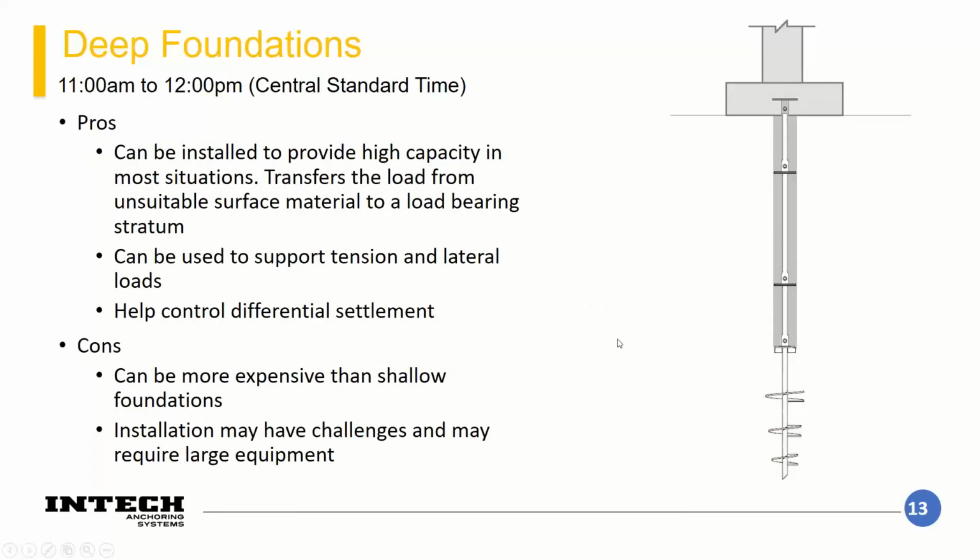So pros of deep foundations, they can be installed to provide high capacity in almost any situation. Eventually, you're going to run into some material that is either stronger soil or rock, and when you hit those materials, you'll eventually be able to get your load capacity. Now, there may be soft soils and buckling concerns or liquefaction concerns that you've got to design that deep foundation for, but you can almost always design around that one way or another to basically achieve the capacity you need using deep foundations.